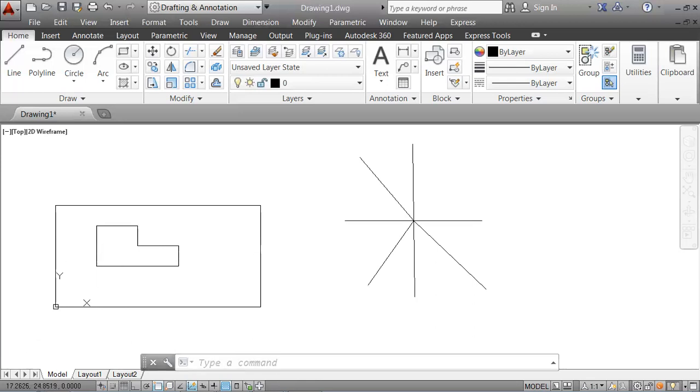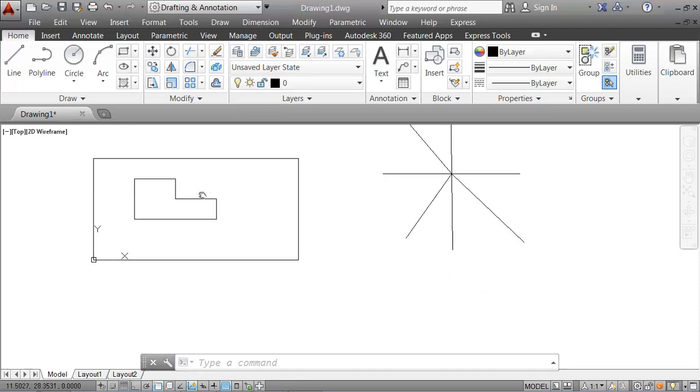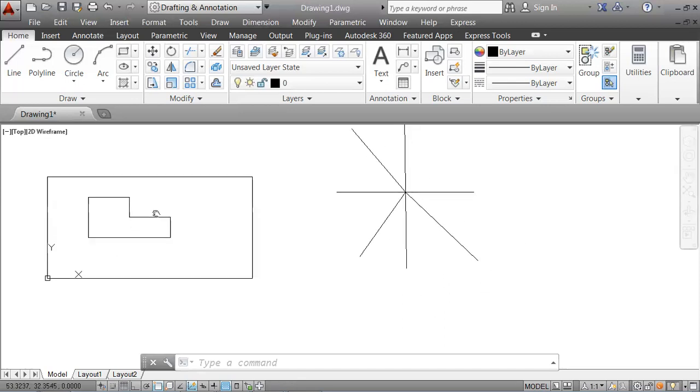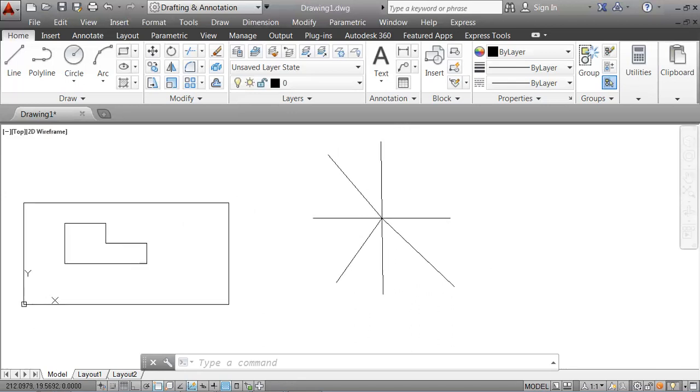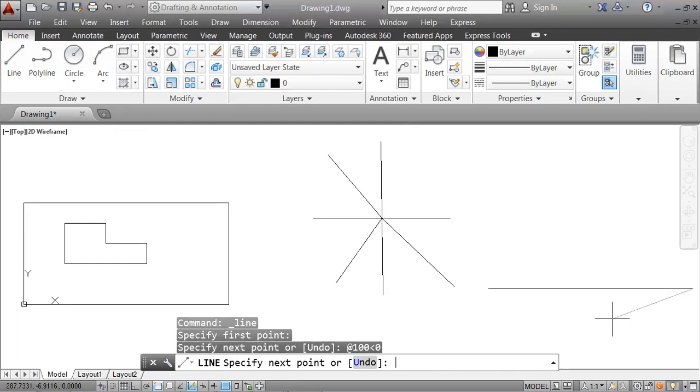Do these exercises, these two exercises. Let's try to do the two of them using the formula here. Line command, let's start it around here, right? And we will say, first line was 100, you said at 100, the sign 0, because I want to go this direction, right?